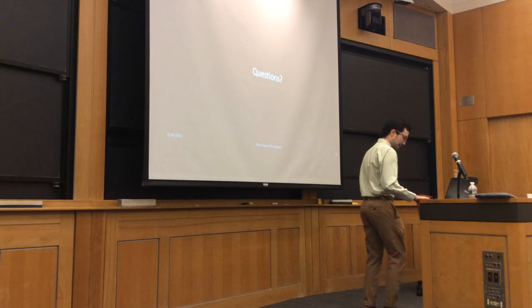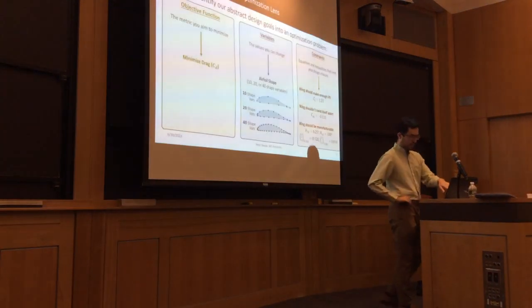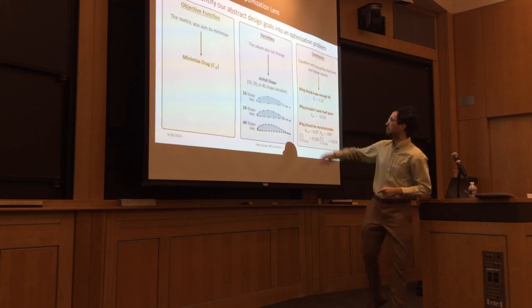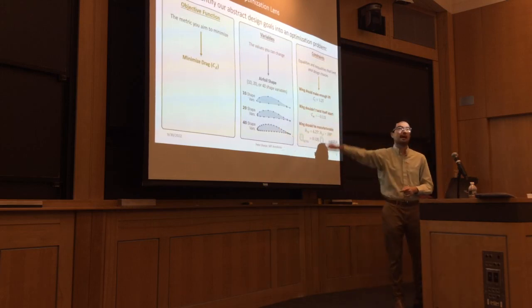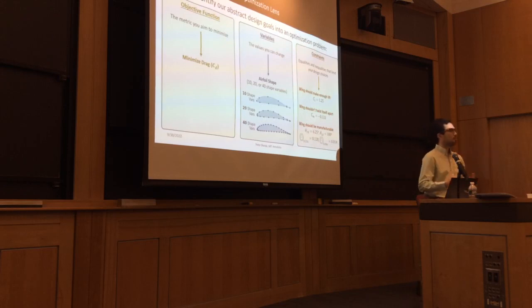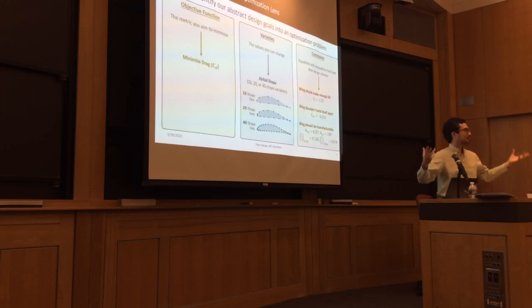Yeah, that's a great question. So I'll get back to the shape formulation here. So there are a couple of different ways. One is if we have a good guess about the airfoil shape, we'll start with that, and then we'll add Bernstein polynomials or Legendre polynomials of some degree with different mode numbers to adjust the shape of that. We can also not start from an initial design, and there's some kind of candidate parameterizations. The long and short of it is that the parameterization doesn't actually matter that much. Once you get above about 20 or 30 shape variables, you can capture most of the reasonable space of airfoils with only a couple degrees of freedom difference between methods.